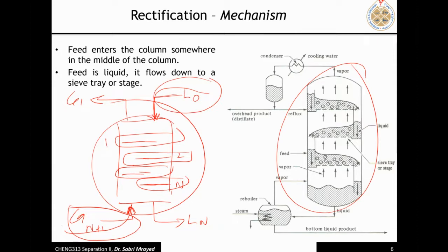Guys, wake up. Do you know what is the type of this data? When you go and solve the absorption problem, where do you get the equilibrium data from? Now, the equilibrium data for the absorption is taking place at isothermal conditions. It's happening at the same temperature and almost the same pressure. But distillation, no. In distillation, we have different temperatures. Each stage will have a different temperature. So where do we get the data in the absorption system? What do we call this kind of data here?